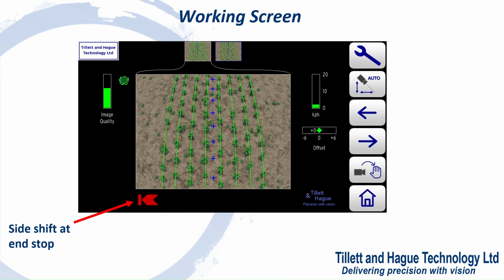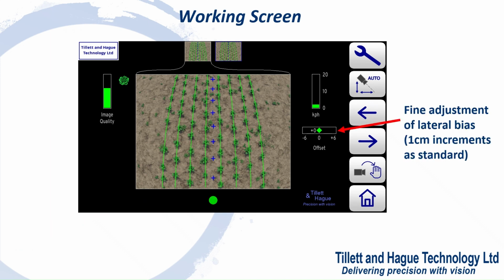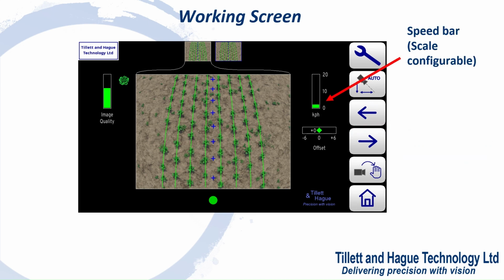A fine offset gauge on the right shows the amount of left or right bias set by the user. This can compensate for minor lateral camera misalignment, crosswinds or side slopes. By default, the fine offset has 6 1cm steps in either direction, though the number and size of these steps is configurable. A speed gauge on the right displays forward speed, which should match tractor speed.